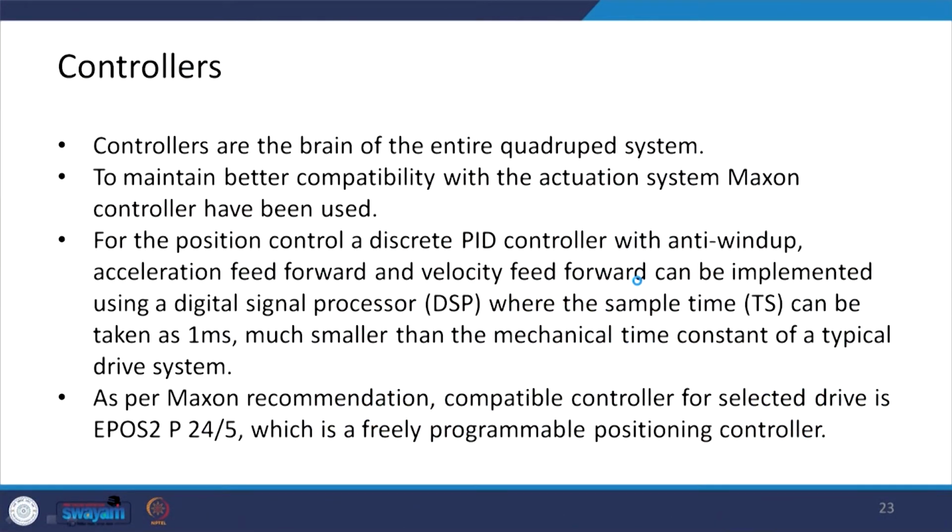The controllers are the brain of the entire quadruped system, and to maintain better compatibility with the actuation system we went with the Maxon controller only. And for the position control, a discrete PID controller with anti wind up, acceleration feed forward and velocity feed forward can be implemented using a DSP, that is the digital signal processor, where the sample time can be taken as 1 millisecond, much smaller than the mechanical time constant of the typical drive system.